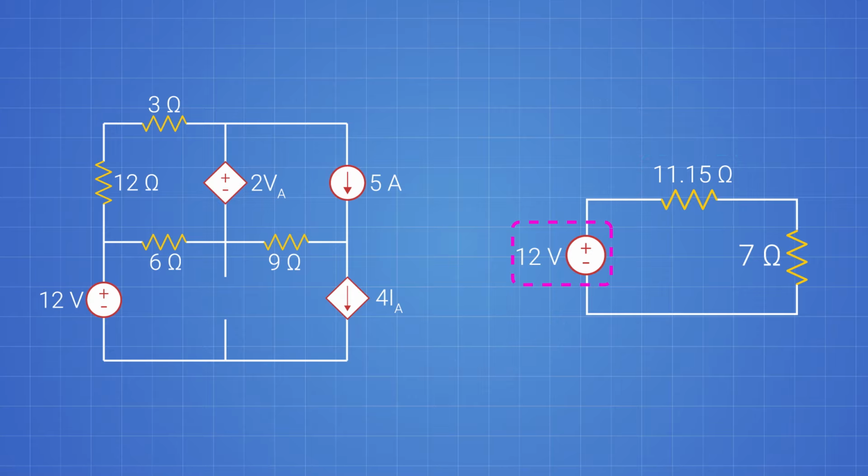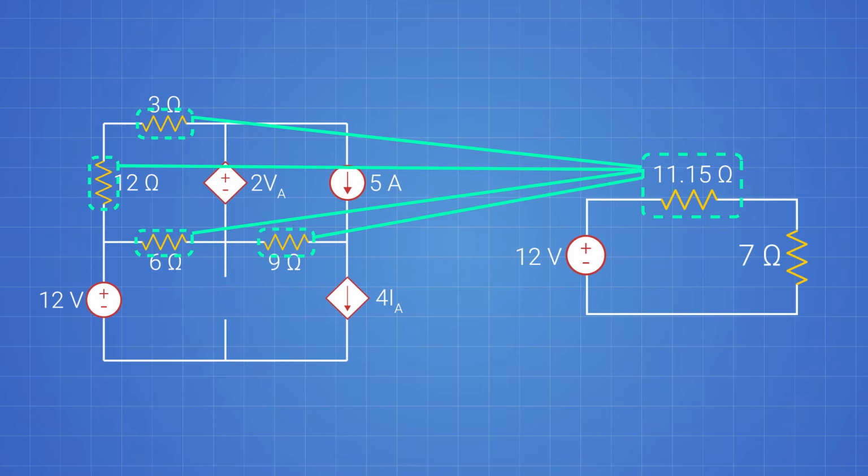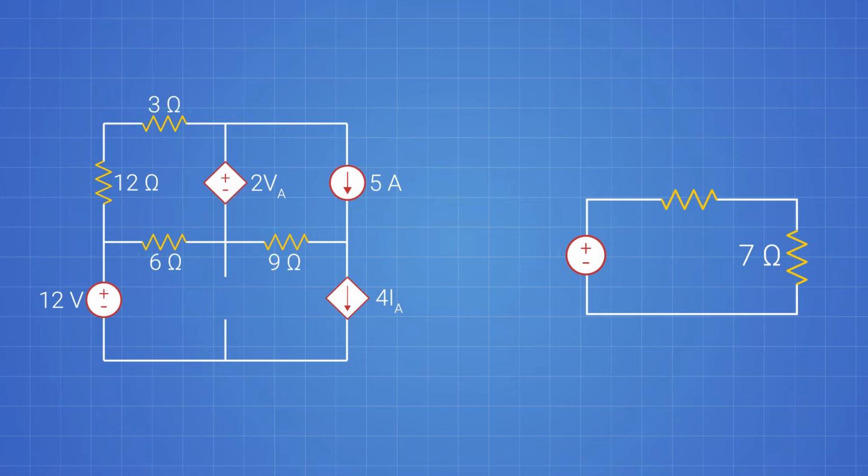In very simple terms, this represents all the current sources and voltages in a circuit as a single voltage source at the place where the load was connected. And this resistor represents all the other resistors on our circuit as a single resistor excluding our load. So all we need to do is just find these two values when we solve a problem using Thevenin's theorem.